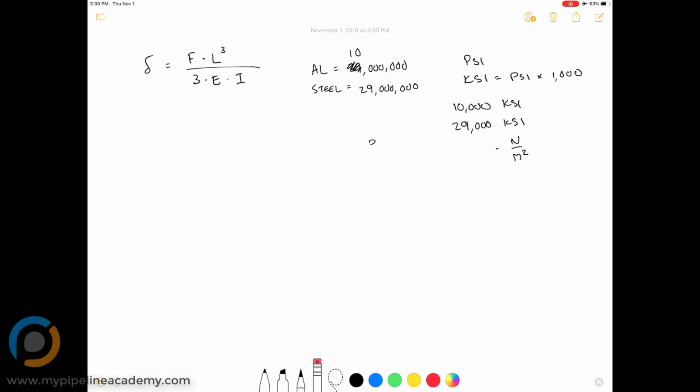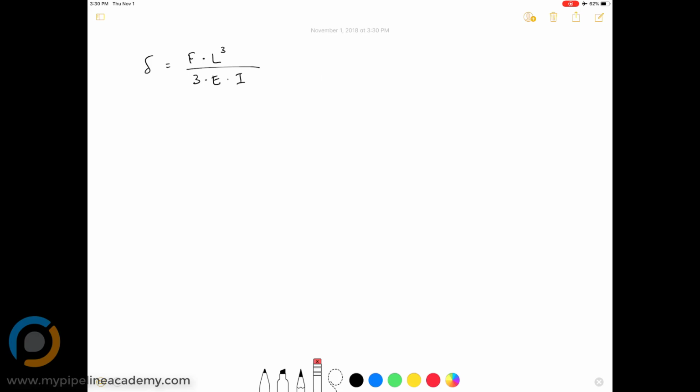Let's erase some of this stuff, and we're going to solve for deflection. We'll do something fairly simple, but let's still look at aluminum and steel. So let's say aluminum was 10,000 KSI, steel was 29,000 KSI. Since we covered moment of inertia in a previous video, we're not going to work out the math for that. Let's just say that we have an example where we've got a cantilevered beam like this, and I'm not even going to specify what the cross-sectional geometry or shape is, because that all goes into the moment of inertia. We're just going to pretend we've already solved for that.